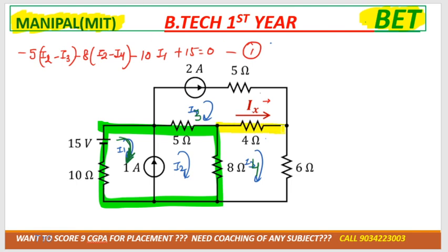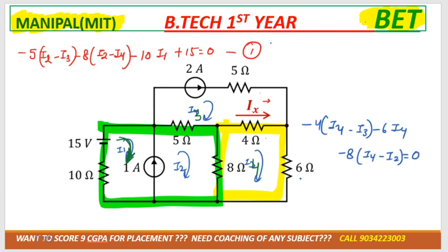This is your first super mesh equation. Another equation you can make from the simple mesh. That would be minus 4(i4 minus i3) minus 6 i4 minus 8(i4 minus i2) is equal to 0. Right? No, you don't need to take ix, I'll tell you about ix later on. We have to take it in terms of what we have assumed, not what they have given. Okay?